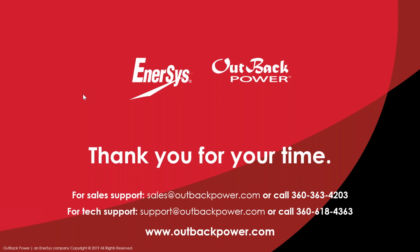Same person, Bill, is asking, with a pre-bundle system like Radian and SimpliPhi, does System F100 come pre-programmed to properly play with the batteries? It doesn't come pre-programmed, but there is a configuration file that you can download from our website and load. That covers all the battery settings. If you have a particular input mode you want to use, you'll need to configure that. And anything that's AC coupled on the Radian is a special firmware version, and you'll need to download that firmware version. So it will not ship pre-configured.